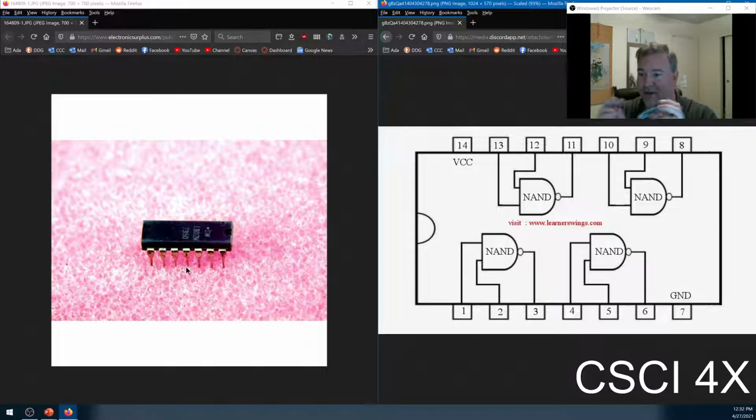You have to set up a pin as being either output, so the Raspberry Pi is going to control the voltage on it. I'm going to make you high no matter what, like a drug dealer, or I'm going to make you low no matter what, like a depressing person that you hang out with. Or it could be an input pin. And so the Raspberry Pi, rather than trying to set the voltage on it, will read the voltage on it.